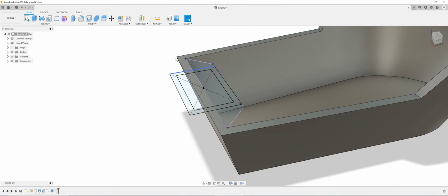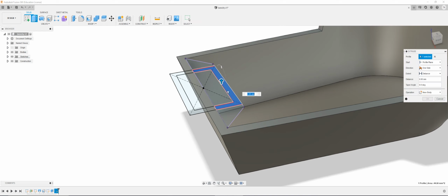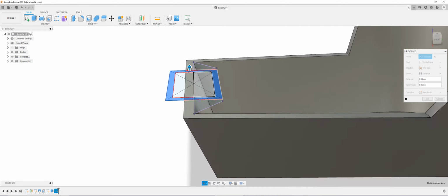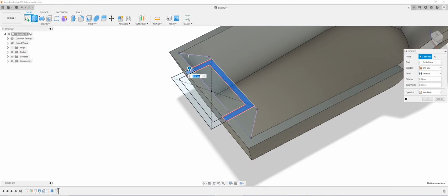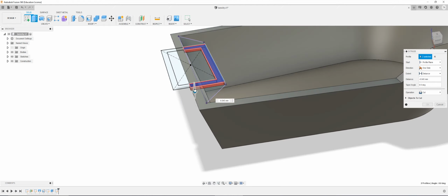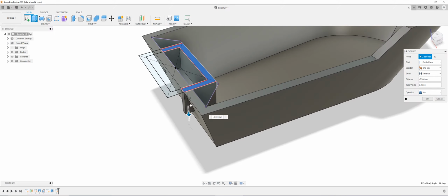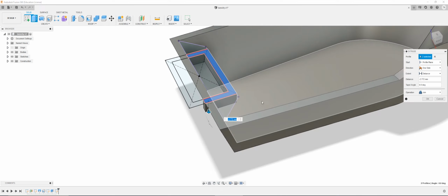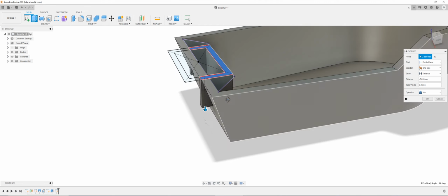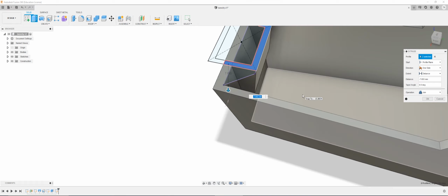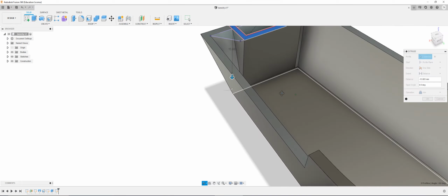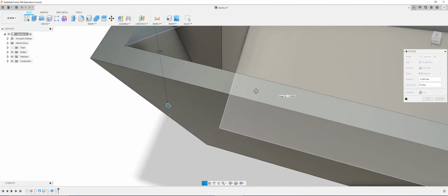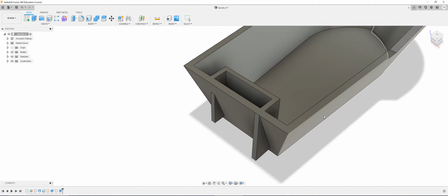And then we're going to extrude. I'm going to select this. You can select the entire thing. But actually, you don't have to. Instead of cutting, we want to create. So under operation, click join. And we want this body to line up with the bottom face of our boat. So instead of trying to calculate how far it is from here to here, we can actually click, and it says snap to a certain value. It's going to line up exactly. And now we're going to click OK.